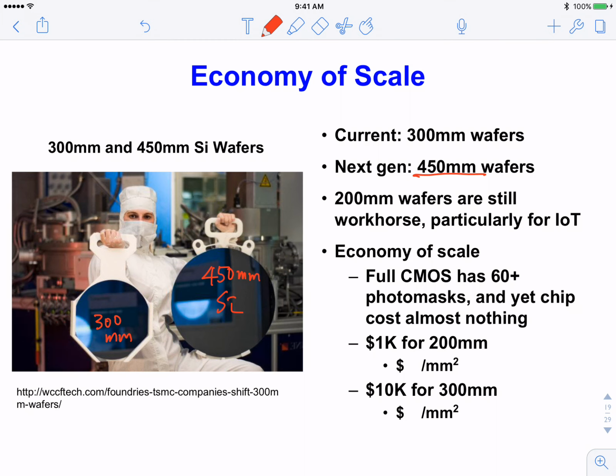And the industry is going in the direction where the size of the platform, that's the wafer size, is growing bigger and bigger. At the same time, Moore's law says for the same area, we are packing more and more transistors onto the same area. And every transistor is getting smaller and smaller. So this is, as you all know, the general Moore's law. And making this transistor, I'm going to walk you through a process making just a p-n junction diode. That's the simplest thing you can make, and you can see how complex it is.